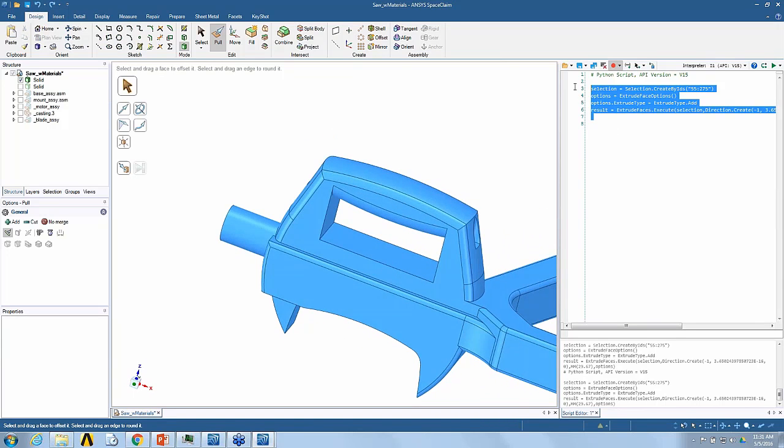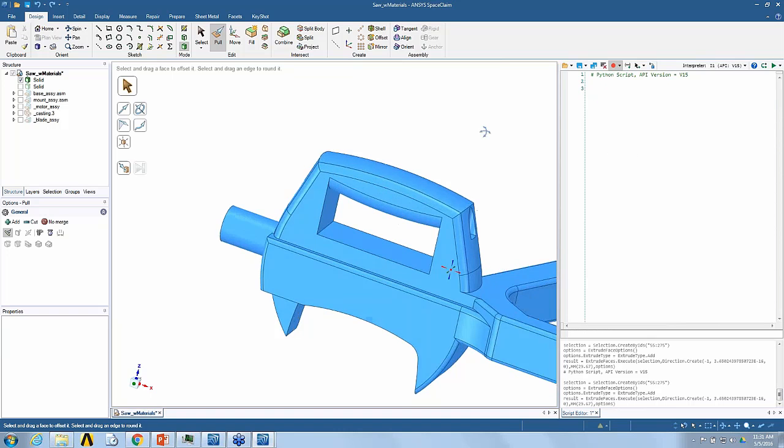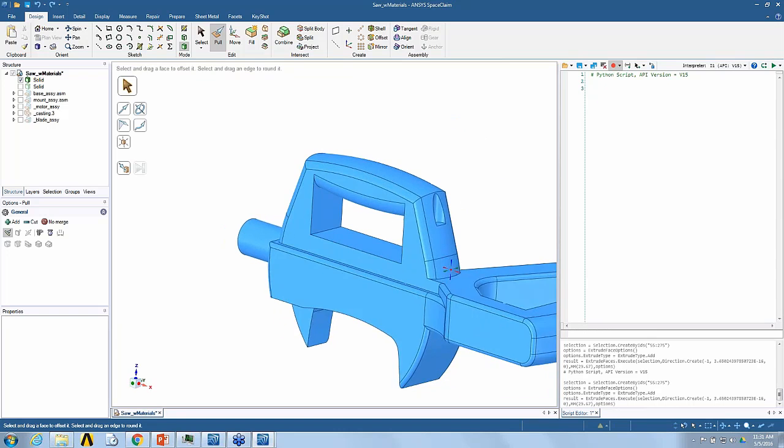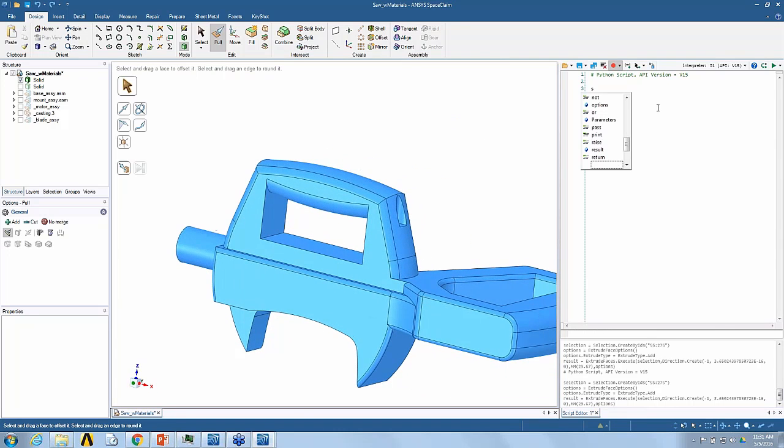Let's look at some other examples. And again, I'm going to use record because I think it's the most powerful way to work with scripting. But let's say that I wanted to remove the fillets that appear here. First, let me show you another one of these examples. So I'll click this snippets example, and I'm going to go here to power selection. Okay, this is the same selection panel that we have over here. And I can pick bodies, edges, faces. In this case, I'm going to pick faces. And you'll see it gives me an option for face area by value. In this case, rounds by radius. Okay, smaller or equal to. And again, this is based on the active selection.